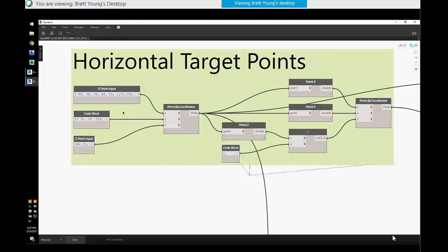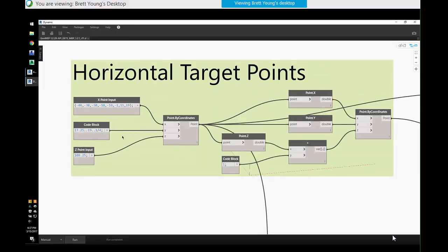right? And so if anyone has any questions on how this worked, but as you can see, I had to manually place the X and Y values of these start and target points just by taking a look at where we were in the plan and watching the points appear and then kind of fudging them around a little bit to get decent places where they should go. There's an automation example of how to make the best placement of these JBoxes as well, not just a fixed location of these target points. But these are fixed and they're hard-coded. But there's definitely some variables that can be placed in this part to get even more solutions to build.